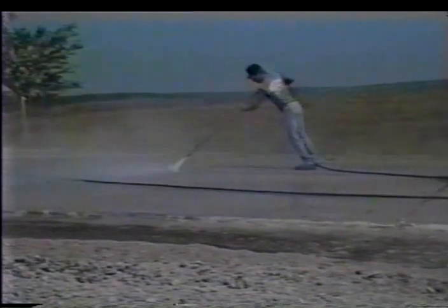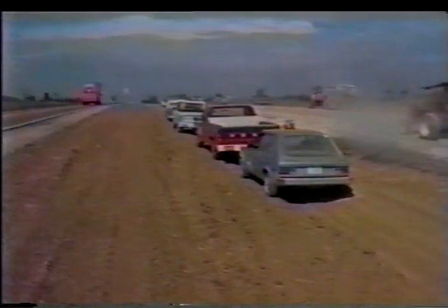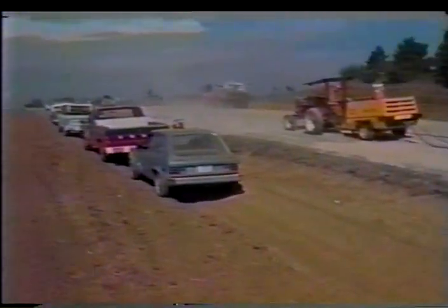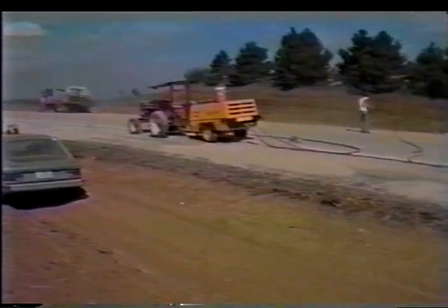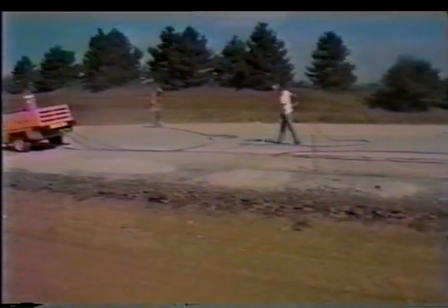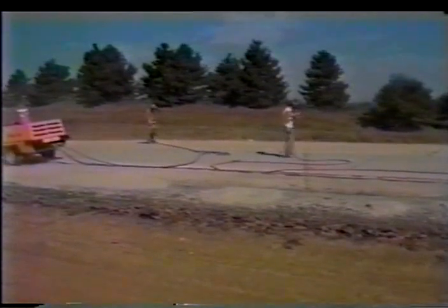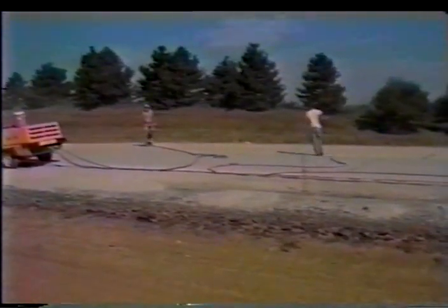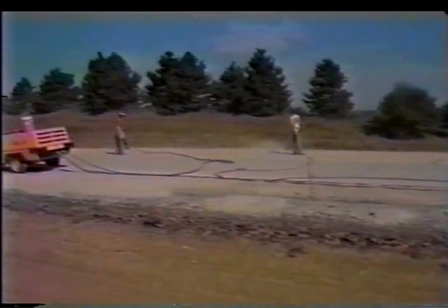Water blasting can be effective for secondary cleaning too, but it requires extra time to allow the prepared surface to dry before paving can begin. Whichever method is used, the prepared surface should then be air blasted to ensure that it's completely free of dust and debris. The air blasting should be done just before the overlaying to prevent contaminants from resettling on the surface.